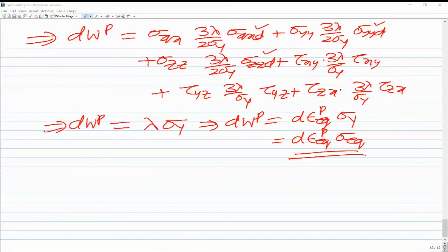But if you use a global coordinate system, the global coordinates of different nodes of different elements are going to be different. In that case, the expressions for the shape functions would be different for different elements. But assume, for my case, that it is a square, that A and B are all one, and according to that I get the 12 shape functions. Then I put that element to all the meshes. So shape function should be the same, right?